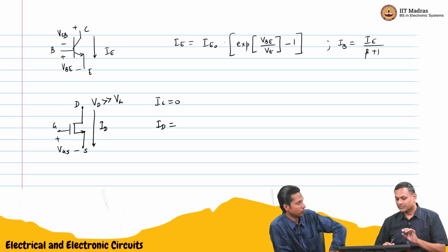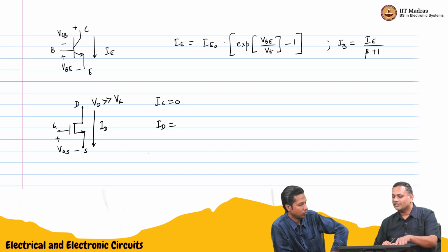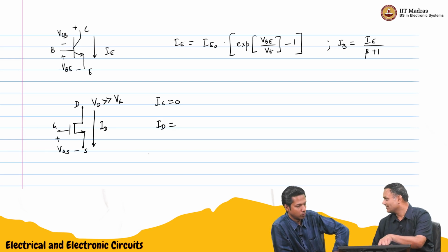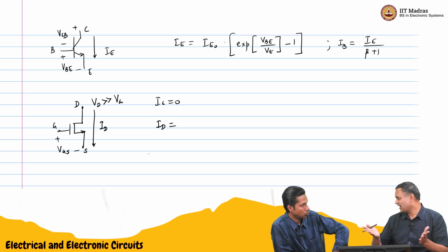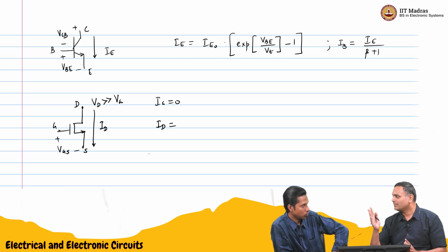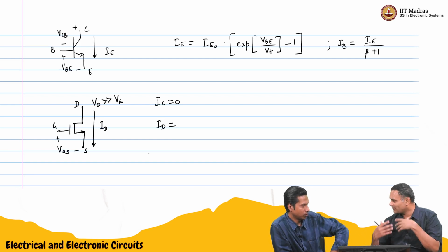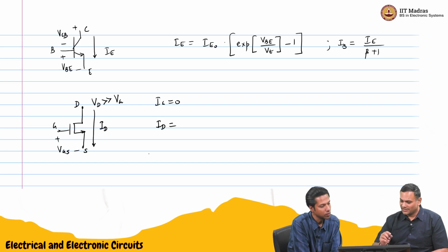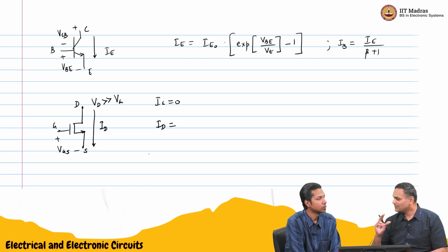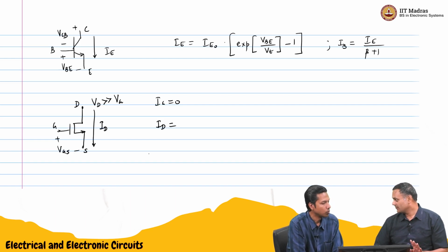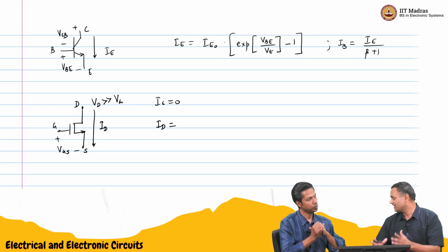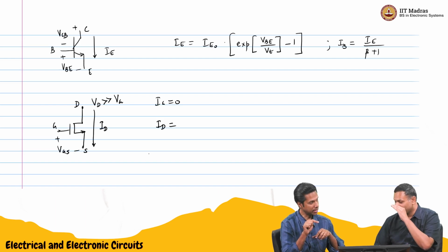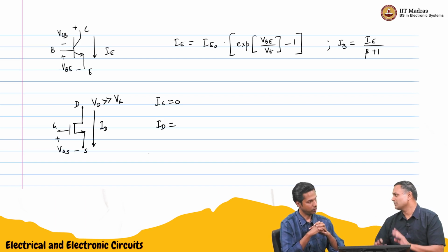First of all, remember this is an exponential relationship. We saw it's like a diode. Until you hit some 0.6, 0.7 volts, it is very low, some small conduction that we very often neglect. It's almost like a knee point where it increases. Same way, the MOSFET also has a voltage till which it will not conduct. In fact, the MOSFET is better. The classical MOSFET has 0 conduction till VGS goes to some voltage.